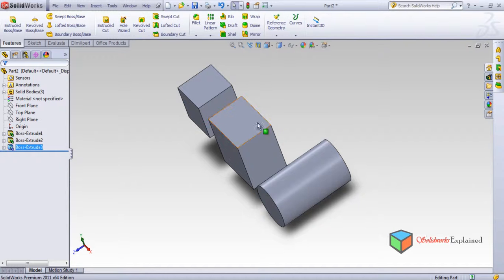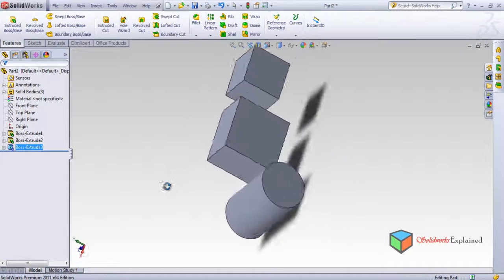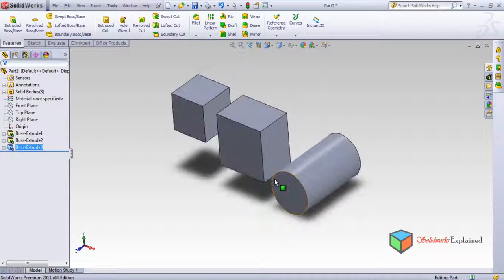Up to surface was this box, which means up to which surface. For example, if we don't know what is the length of a particular object, so up to that surface if you want to extrude, we can use up to surface. And mid plane means from the mid plane it is being extruded on both the sides. So this ends our extrusion session.